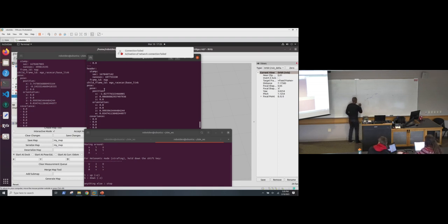So if I wrote my own node here, subscribed to that, I could just keep that information and retain it there too. So I have some kind of loop like we were talking about earlier at 10 hertz or whatever, and I could maybe make a vector of poses and append to that vector every time I got it, and then maybe look at delta poses and see if it's doing something differently, or figure out how it went around the left corner, by where it changes in orientation. A little bit of logic there.